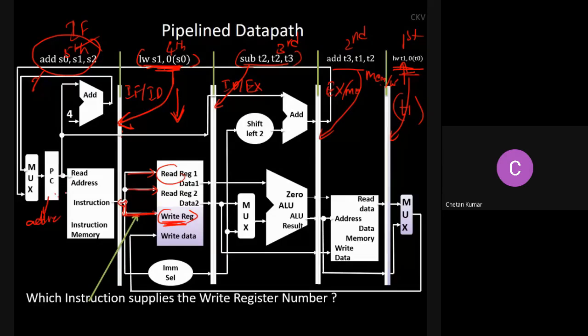During the clock cycle, it would take this PC content, read the memory, and the instruction code for the add instruction might be available at the output. It might not yet be loaded into the IF/ID register. It will be loaded into the IF/ID register when the next positive edge comes. But in the current clock, if I am sampling some time duration within this clock, then this is the status.